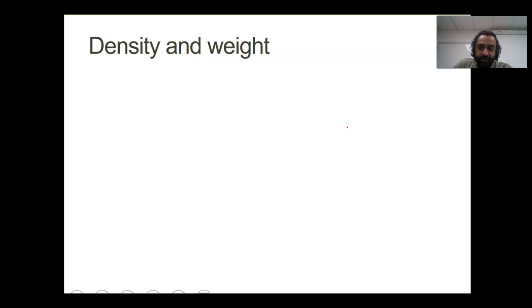So that's a very interesting relationship. We have to think about volume. Why? Because we have to know how much insulation we need to pack for that little volume. So, the density and weight relationship: when you go and buy blown-in insulation, you might want to go with weight, and you will sometimes have to fluff the insulation, especially the cellulose, to achieve the right density.